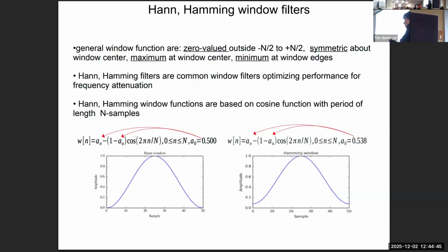The rolling average filter is just averaging the nearby samples, the neighboring samples on the input, with equal weight. So it just takes an ordinary, regular average of the samples in your window, and that produces a filter. You can improve that filter, meaning you can improve the transition between passing a signal and attenuating the signal, by taking a weighted average of the samples in your window.